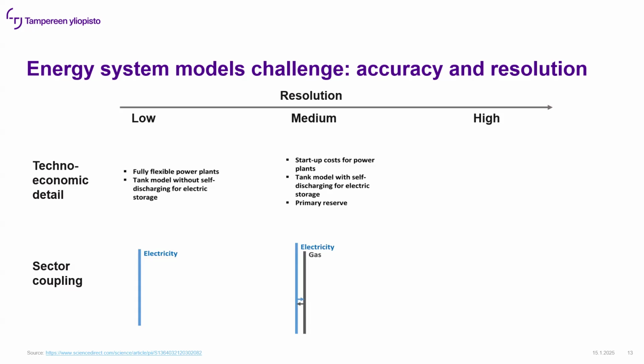There was actually another type of gravitational energy storage. For example, in Finland, they're trying to make it in an abandoned mine. So 530 meters. So you have a mass in there. So you hoist it upwards and lower it downwards. So there's an electric motor and it can act as a generator. So whether you're lifting it up when the electricity price is low or lowering it down when the electricity price is high.